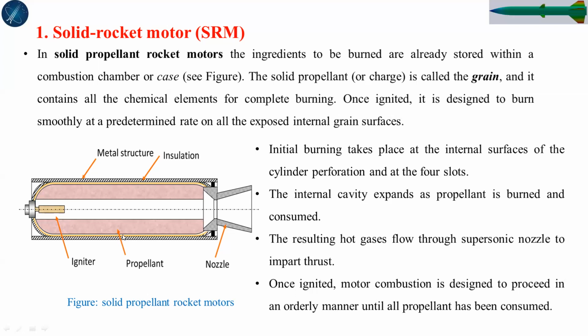What is the cylindrical casing? What is the size of the dimension? What material is it manufactured from? What is an appropriate insulation material required? And what type of igniter? We have the pyrogen igniter or we have pyrotechnic igniters. And how can we design the nozzle itself? Nozzle design is a very critical issue. So you must consider how to design it. Just search many books on this and try to design the nozzle from this time onward.